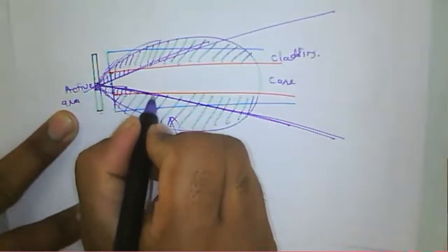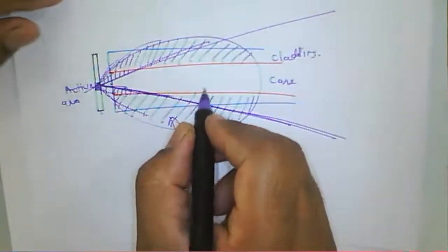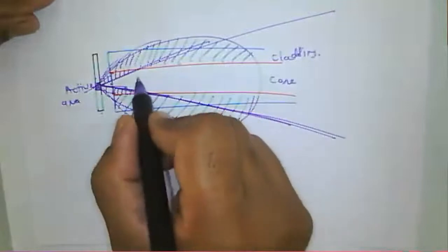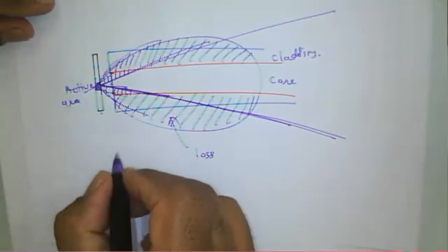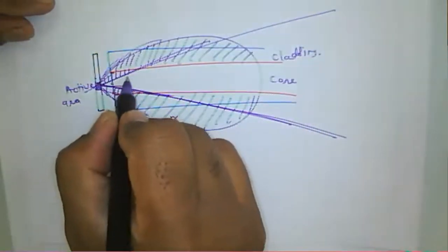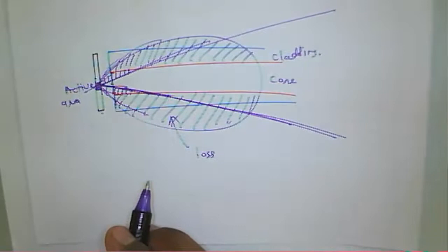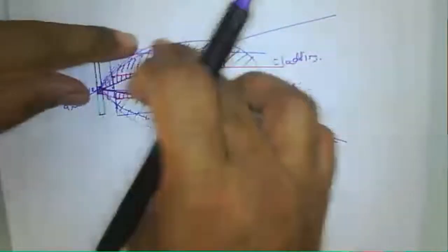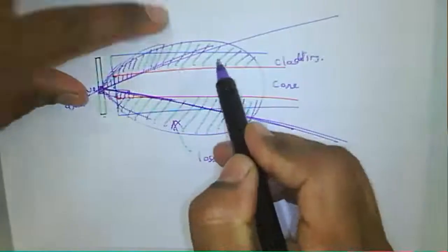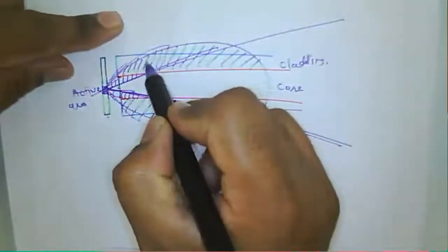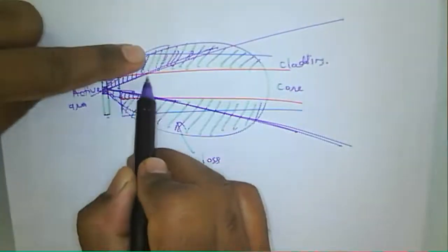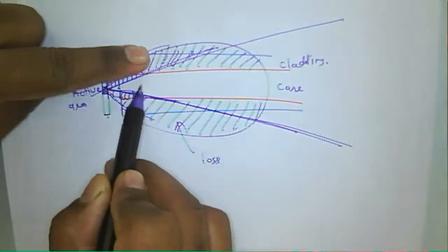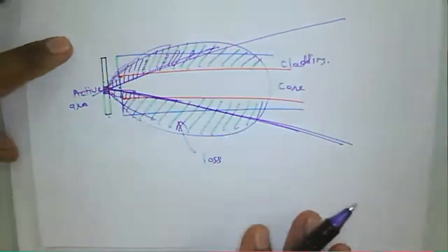Okay, here we can consider that this one is nothing but the acceptance angle of the given particular fiber. And we say that this is about radiation, and here we have the acceptance angle of the optical fiber. So the light outside this angle will not propagate inside the fiber because it is not a part of the accepted light; it will be the radiation pattern. Only the signal from this particular region will be propagating into the fiber.